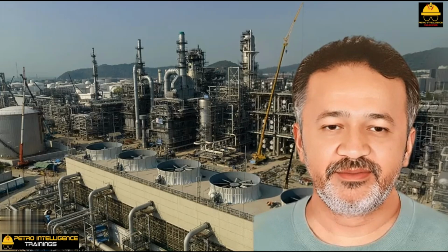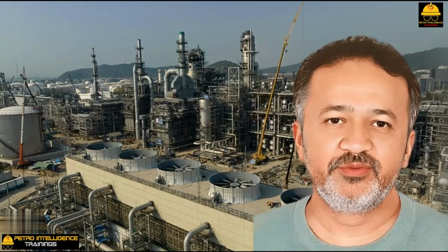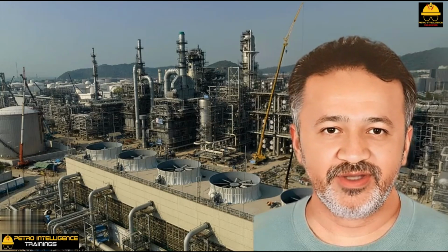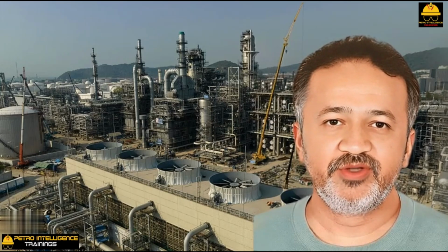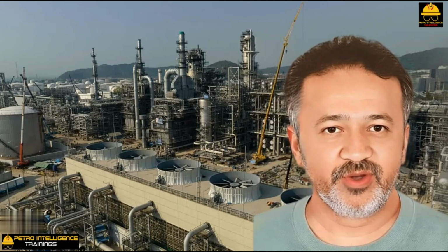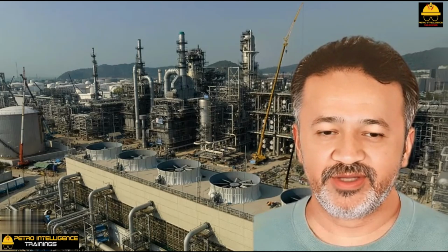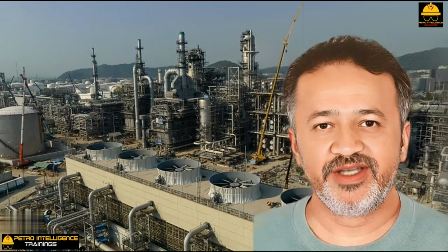Air-cooled condensers. In many process plants, the pump alleys are covered with forced draft, air-cooled condensers. Dozens of coolers are arranged in parallel. I have seen services where 300 MMBTU per hour of condensation duty was easily handled by aerial cooling.